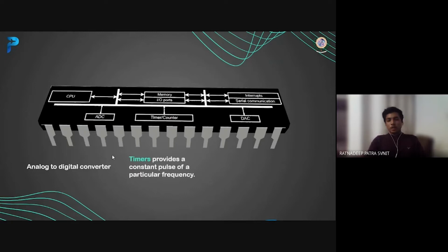Okay, so next is the timer and counter block. A timer is basically a block that creates a continuous clock signal pulse. So what exactly is a clock signal? A clock signal is just a rectangular pulse of 50% duty cycle, and this rectangular pulse has a very high frequency. Basically, this clock signal keeps every other block shown here, all of those blocks, in sync. So that is the work of the clock signal.